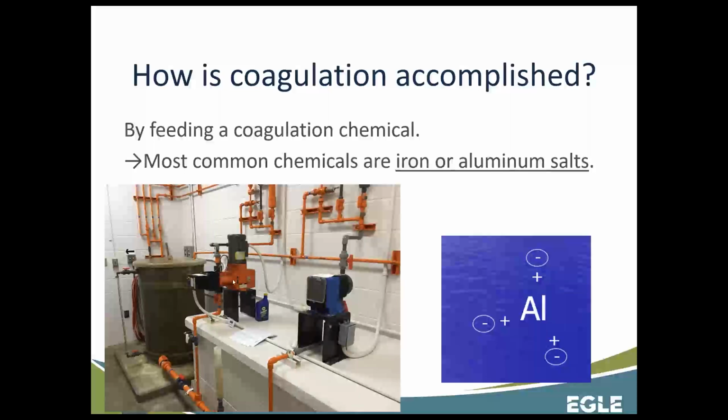Up here on the counter, we've got our 2 feed pumps. We have to have redundancy in case one of these pumps fails. There's another one that's ready to be put into service immediately. Typically, these will be the same model pump. In this situation, you can see that they're 2 different ones. My guess is one of the pumps failed. They decided that it was a little antiquated or that they'd like to change to a different model. And when the second pump fails, they'll probably go ahead and replace it with the same model.